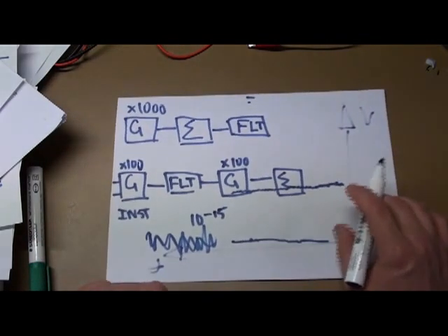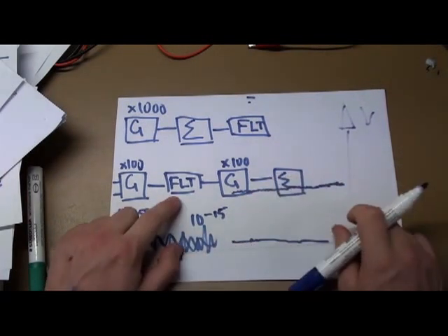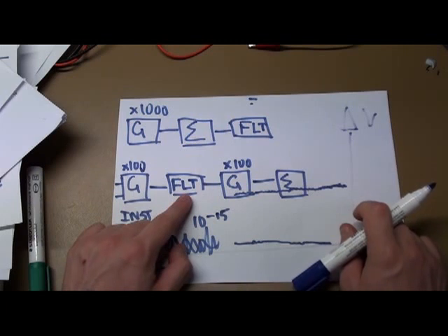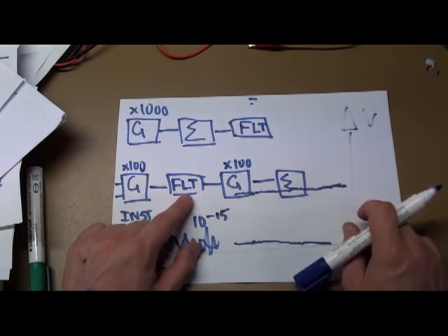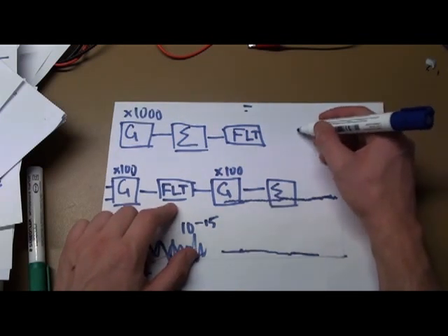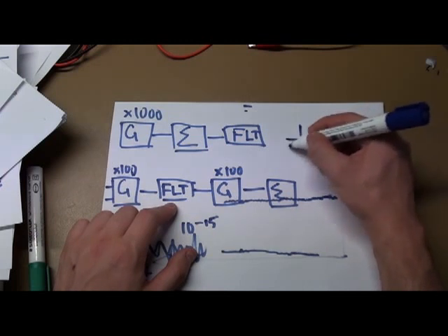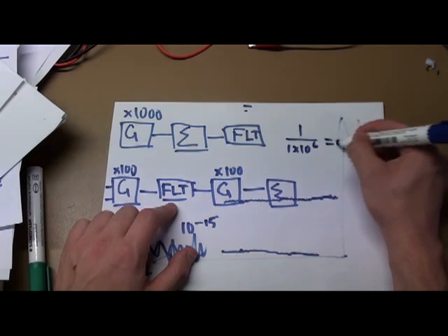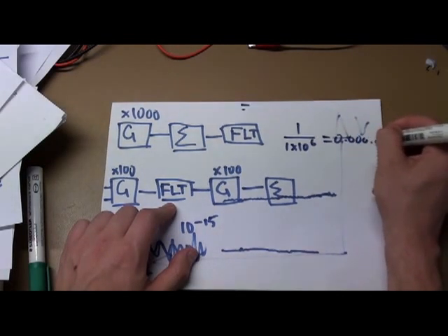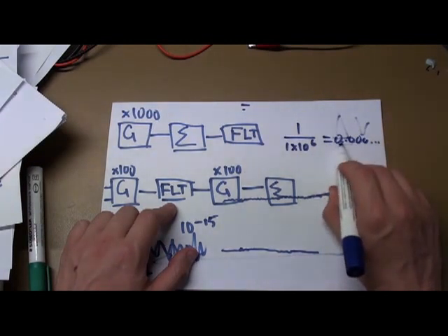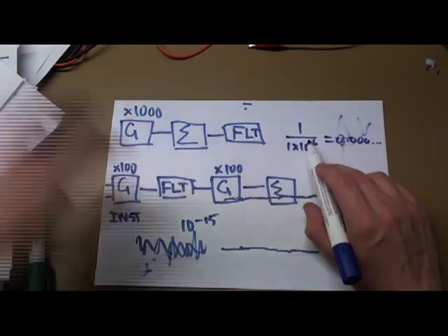And so the last thing to talk about is picking a frequency for this filter. Now if you think about how fast the strain gauge is going to be loaded, it's not very fast compared to 1 megahertz. So 1 megahertz, if we use our formula from before, will be 1 on 1 times 10 to the 6, which equals 0.000, well, you get the idea. So the time it takes to cycle is really fast. So if we had a 1 megahertz signal, we want to get rid of that.